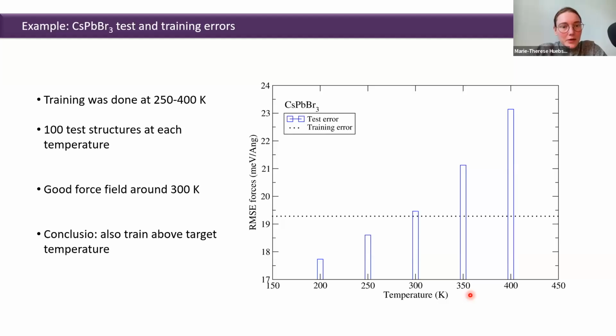Then maybe let's close with one more question that is very much aimed towards molecular dynamics, because that is also what we will discuss in the hands-on today. So I'm reading out loud. In my experience with building models using the VASP MLFF, I've noticed that dynamic parameters such as the Langevin gamma setting in the training phase seem to impact the result, possibly influencing the final MLFF parameters.